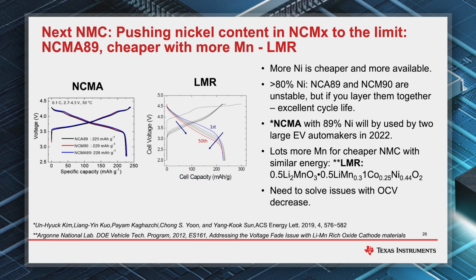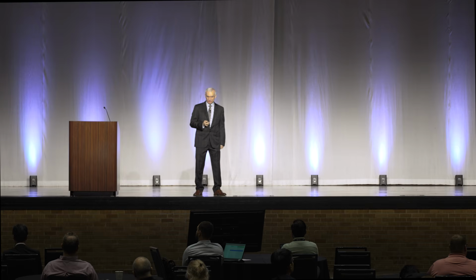Right now, there are some problems that have to be solved with it. One problem is that the voltage is actually unstable and changes with the cycling. And you can see here in this picture. By itself, it's not terrible, but you do lose some energy density when doing that. And so your energy density basically decreases with cycling faster than it otherwise would. Second, it causes a problem for gauging as well, because now in our gauge, we have to account for the change of voltage with the cycling. The same thing, by the way, happened with silicon as well. So we are actively developing algorithms that will continuously model and change the voltage with aging.